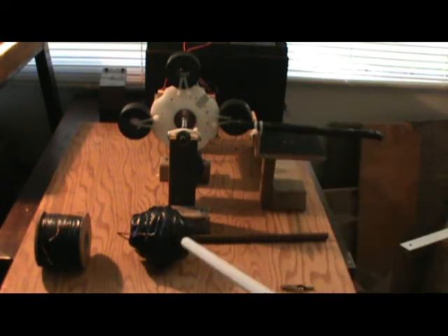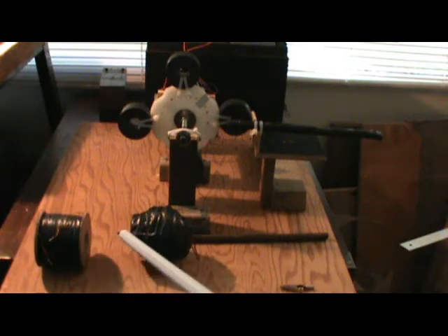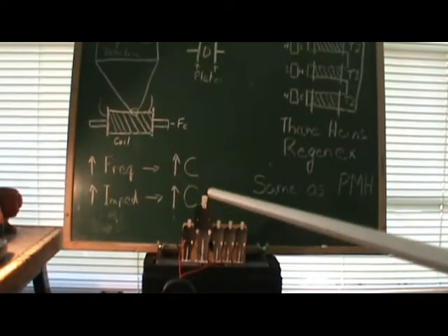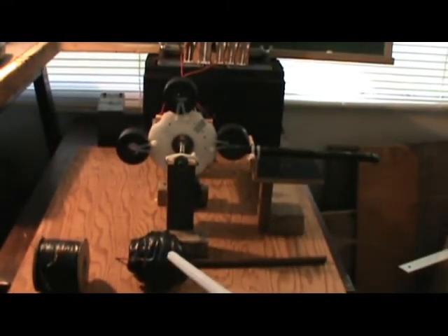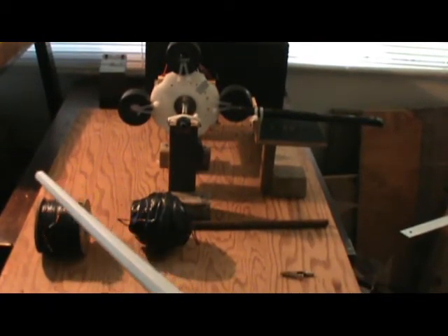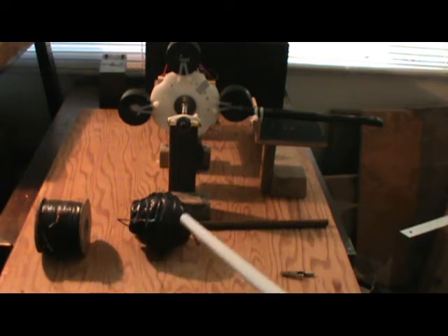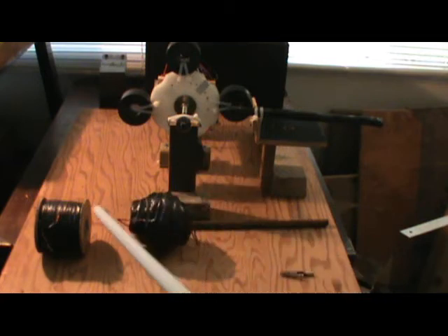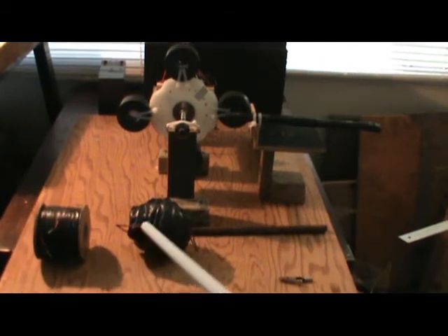But there should have been a difference between these coils because they're very, very different in wire gauge size, and thus at the same frequency there should have been a different capacitance. Because this coil, I already know, is less than 1 ohm. This one is over, what is it? I want to say 18 ohms. This is less than 1 ohm. Somewhere near 18. Dang, I should have measured them. I wasn't thinking. But I bet if I did measure them, that's what they would be.